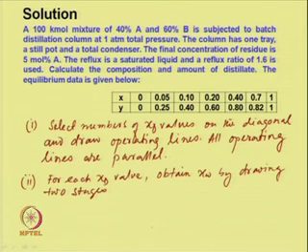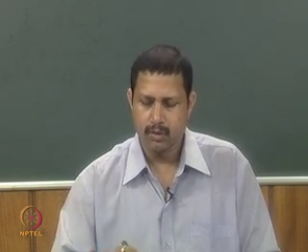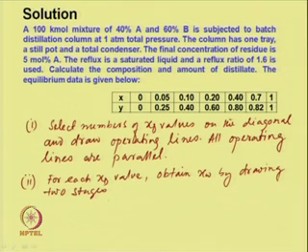Two stages means we have one tray and one still pot. So, we will consider the still pot as one tray, as we considered the reboiler as one stage in the case of the fractionator. So, it will be one equilibrium stage. In this case, we will draw two stages and obtain the values of x w corresponding to a particular value of x d. We will have a set of x d, x w values.